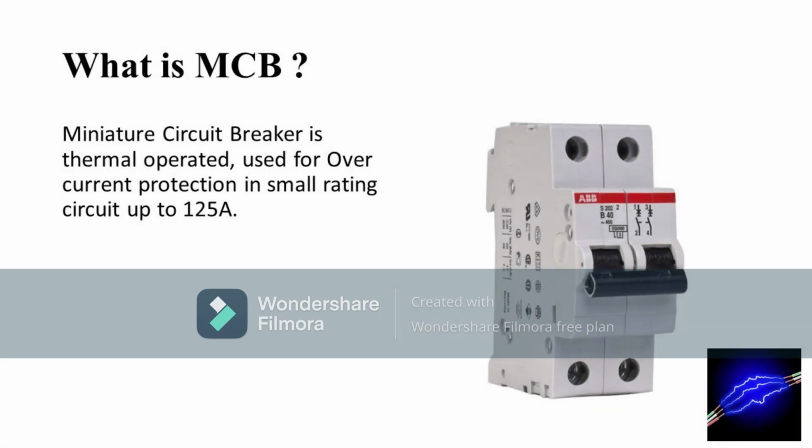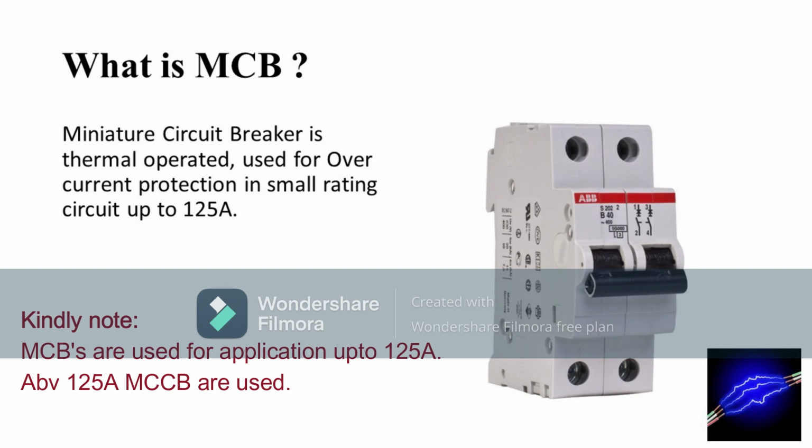So what is basically an MCB? MCB is miniature circuit breaker. These are widely used in electrical distribution boards to protect circuits from overcurrents and short circuits. They provide a crucial safety feature in our electrical system. MCBs are basically thermal operated devices used for overcurrent protection in small rating circuits up to 125 ampere. Above 125 ampere mostly MCCB is used.